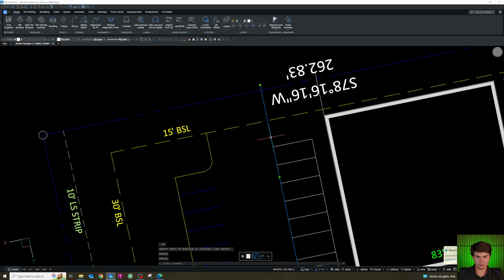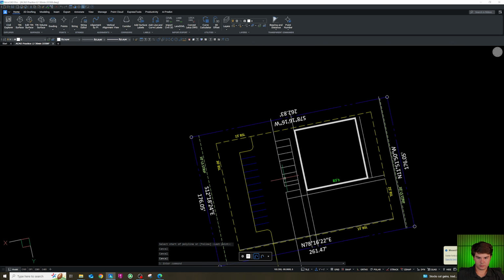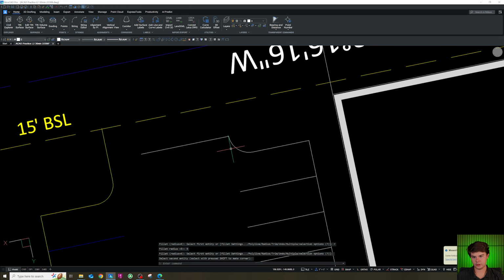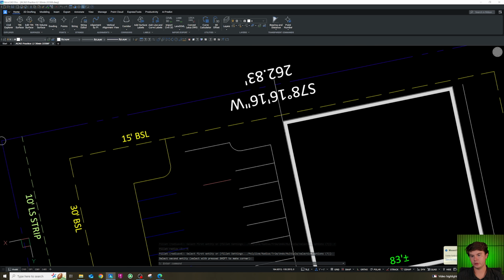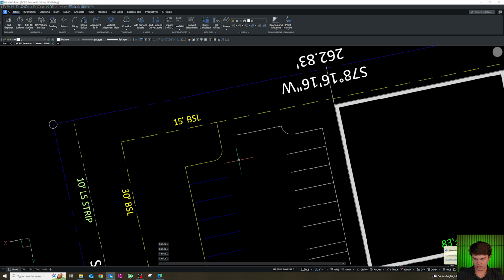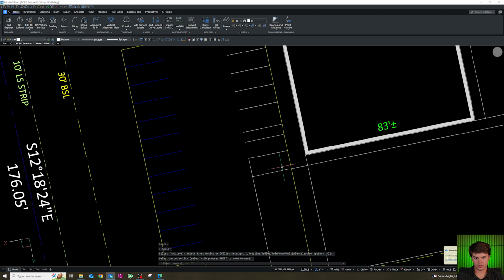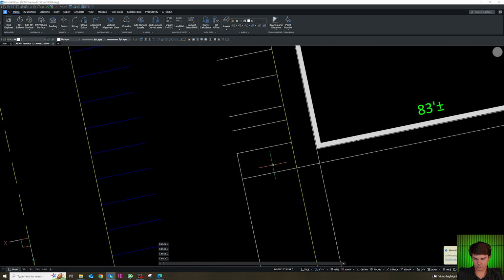So now we typically go 5 feet from the last parking space and then over. This just gives us room to give us a 5-foot radius here, and if a car is parked right here, it'll be able to turn around and get out. And then we'll connect this back up with a 0 radius here. Perfect. And now, since this is a 9-foot island, we'll do 4.5-foot radius.